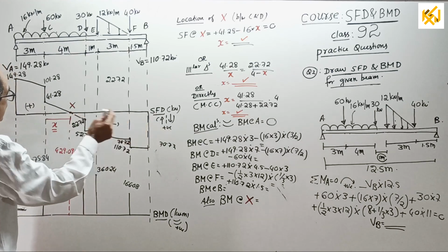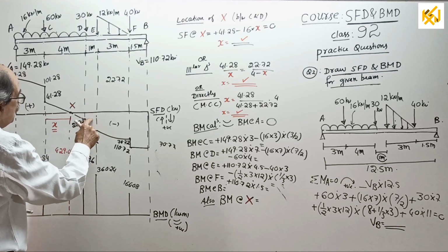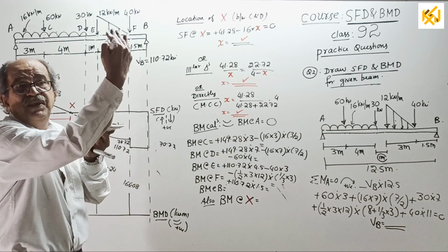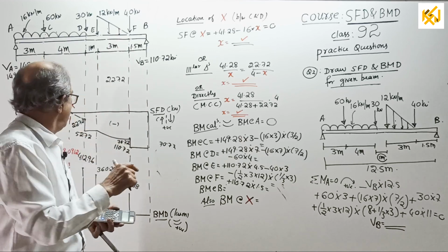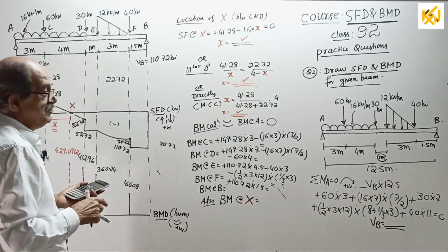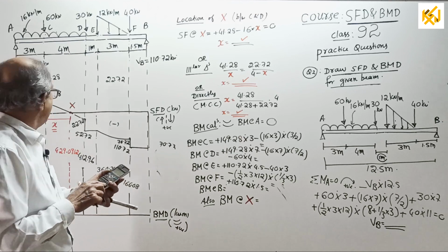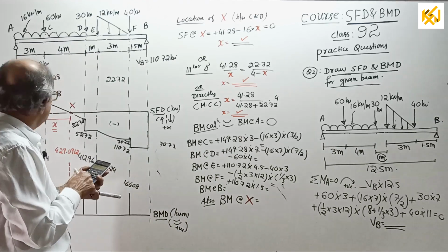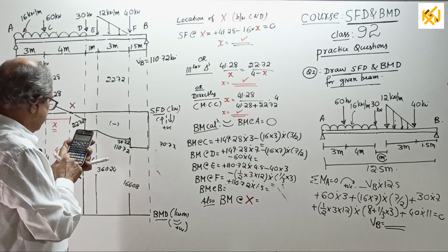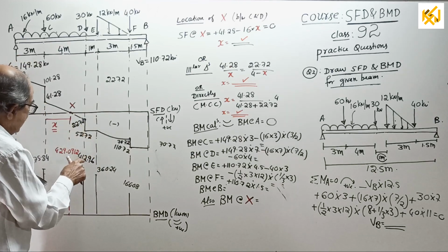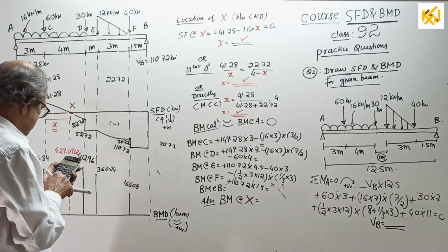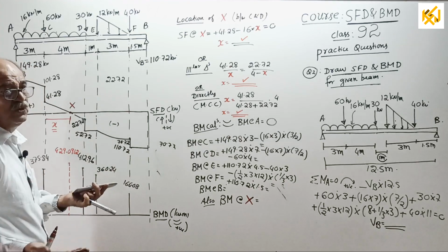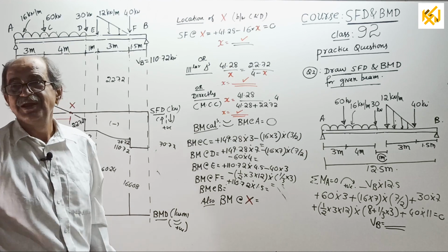Or if you look this side, this shear force is negative, but no, even if it is negative, right side up is negative, so you should take plus only. 22.72, anyway when you are squaring, there is no effect. 22.72 square, divide by 2 and divide by how much? 16. Then add whatever BM you got here, plus 412.96, 429.0912. This is a perfect check for me.